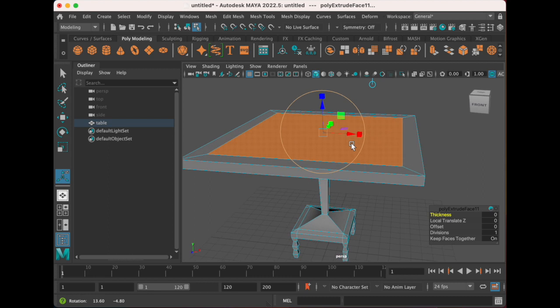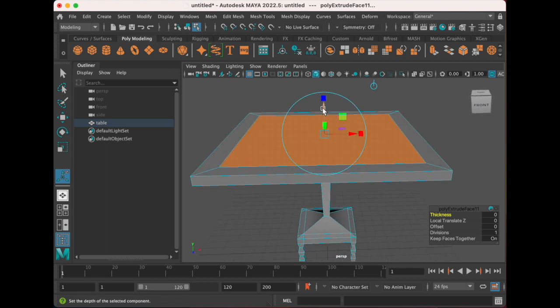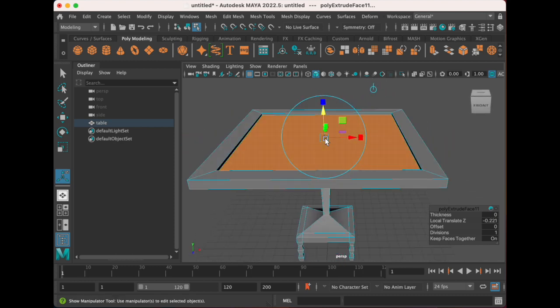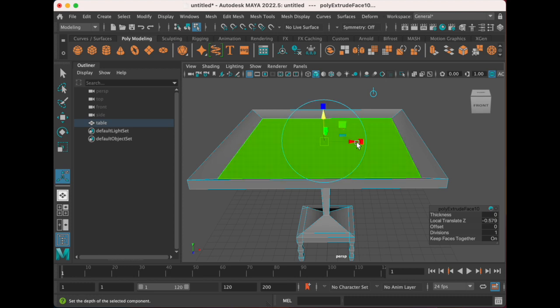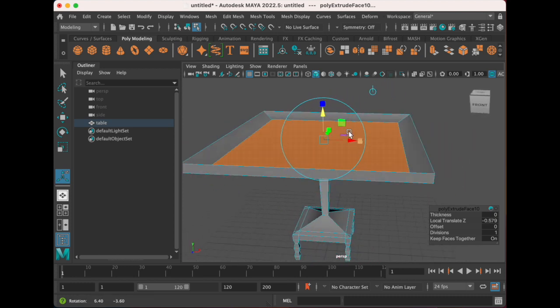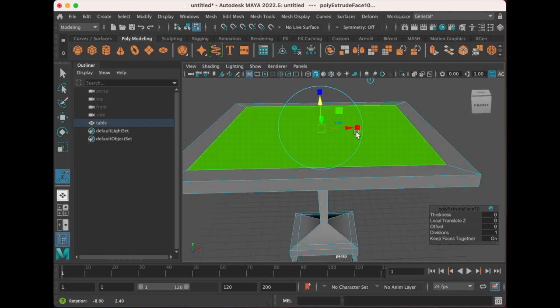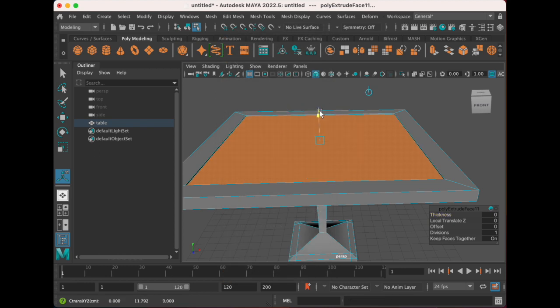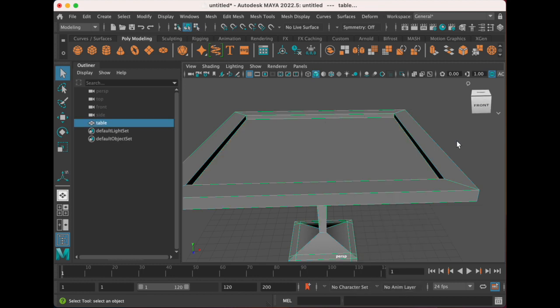And if you notice, I did not just go to the arrow. I did an extrude first, because I wanted to have this little bit of a drop like that. Be careful about just moving things down. If I had not done this extrude and I just used this arrow, okay, it would have done this, which is not as appealing. It kind of has that slide down the sides. So be careful about that. Again, I'm gonna do one more extrude up here. Okay, and then bring that piece down. All right, and then right there we have our table.